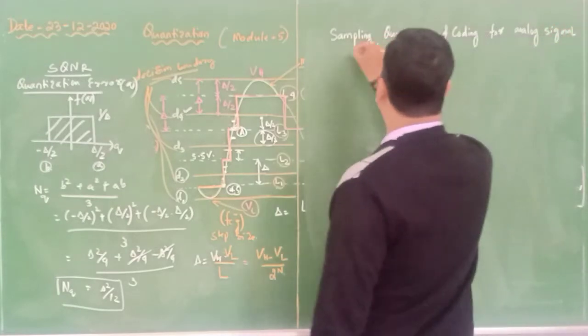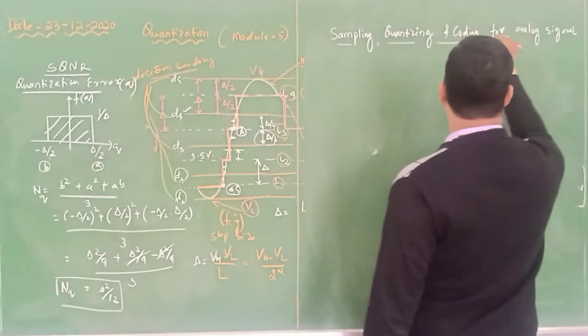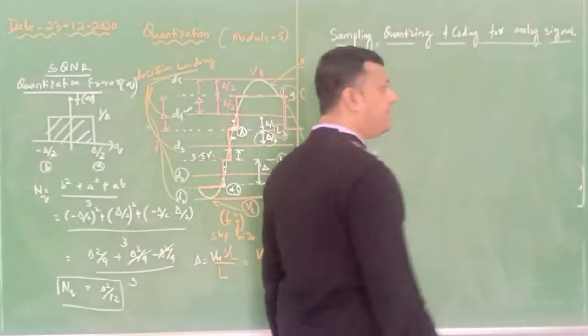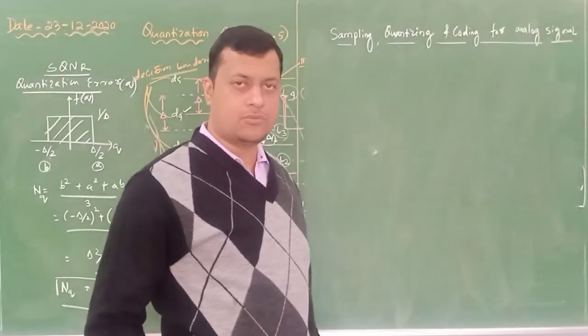So first we will sample, then we will quantize, and then we will assign the binary bits to that particular value.